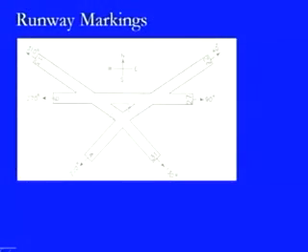Here in this diagram we are trying to show again that there are a number of runway strips which are intersecting with each other. In that sense, here this is 13, this is for this direction. So, this is 130 degrees, whereas when we are looking at 31, this is for this direction, it means we are going in at an angle of 310 degrees with respect to the north direction. Similarly, this is 27 because we are going towards 270 degrees, or this is 9 because we are going towards 90 degrees. So, it is all with respect to north.